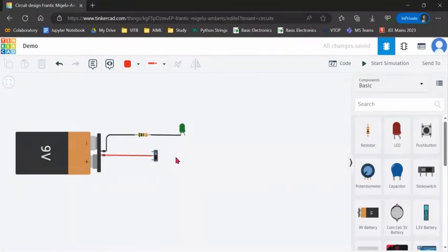Okay. Now, if we place this switch button up, terminal 1 will be activated and we should be connecting here. If we connect terminal 2 with the LED and place the switch button to this side, this will be on. Terminal 2 will be on. Okay, this was the common one. So common will be connecting with the battery and output we can take from any of the terminals.